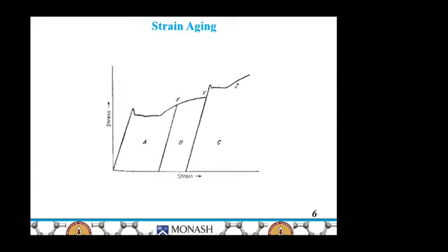So if the specimen is unloaded after point X and retested without any appreciable delay, without any wasting of time, then no further yield point phenomenon will be observed in this case, since the dislocations have been torn away from the atmosphere of carbon and nitrogen.